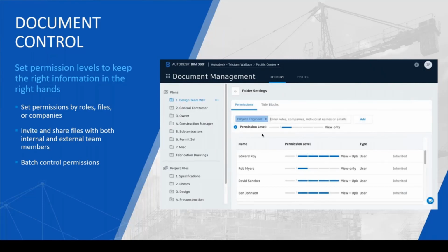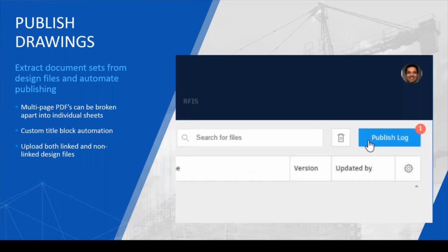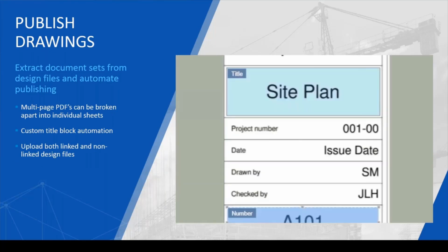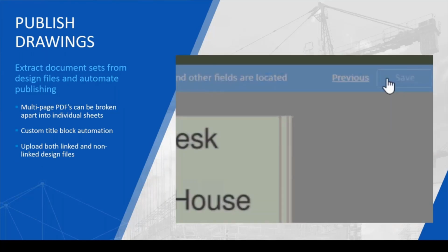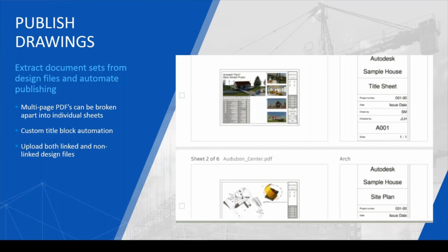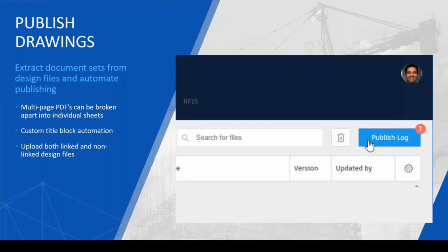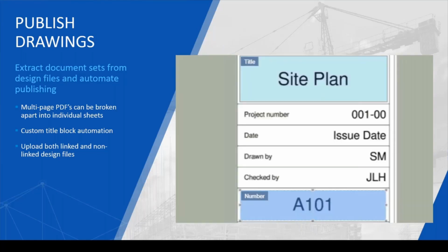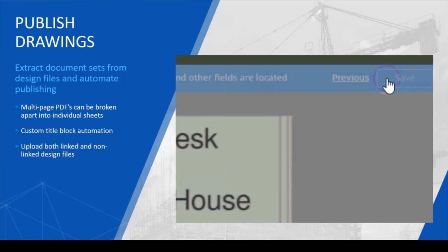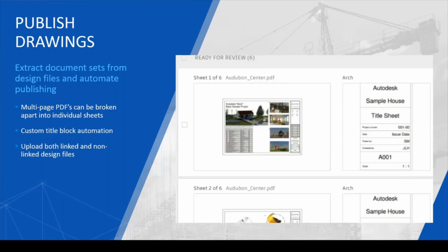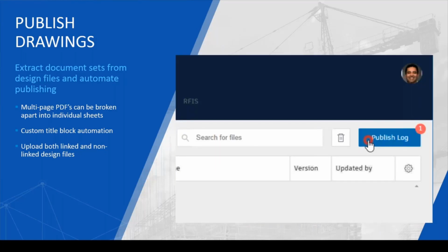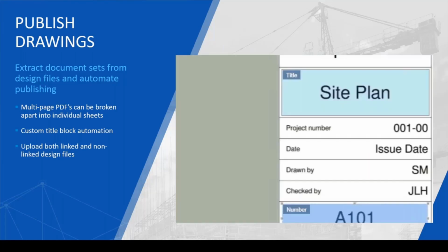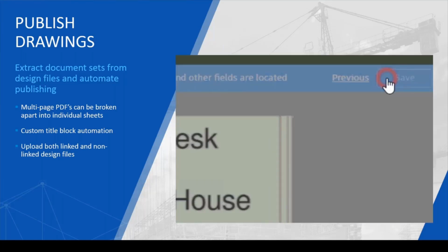You're also able to publish drawings, and there are a number of ways that you can do so. You can share them from within BIM 360 Docs via PDF or Revit files, but you're also able to upload documents in a number of different ways, and this includes directly from within Revit. This is a new add-in, only since Revit 2019 or 18.3 of this year, I think, and it's available in all the latest versions of Revit 2019.